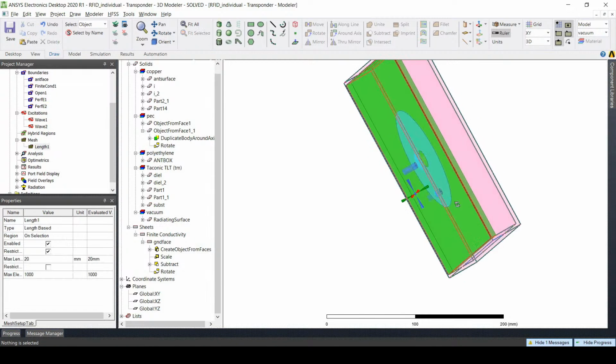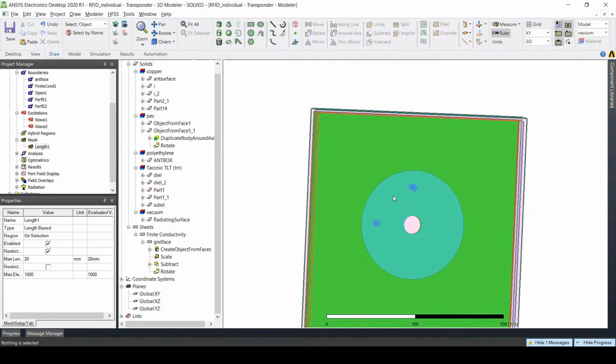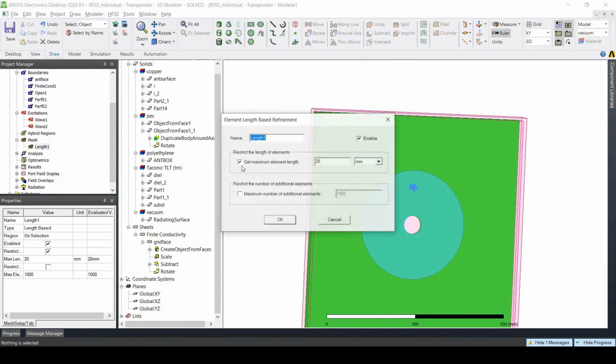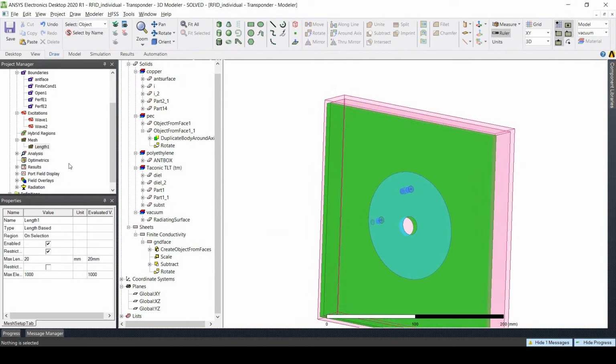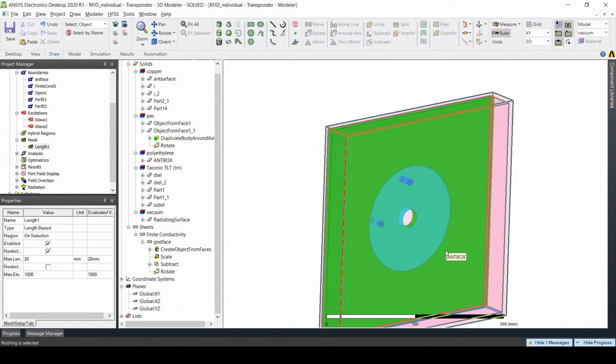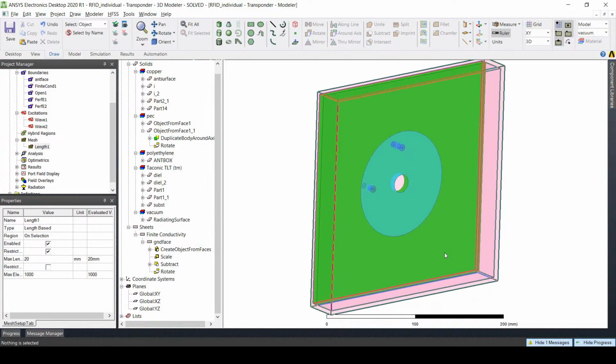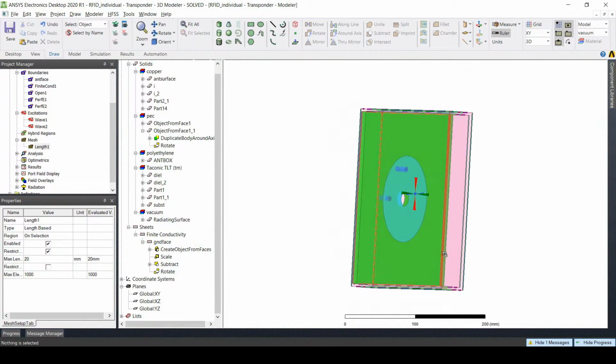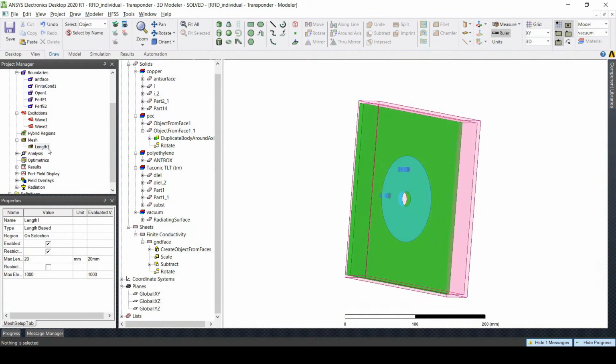here I set up a mesh size for our antenna. If you are not working with a fairly large or fairly small system, you can just ignore your mesh unless you want to get a more accurate result. With the default mesh, HFSS can give you a very decent result already. So you don't have to set up the mesh all the time unless it's required.